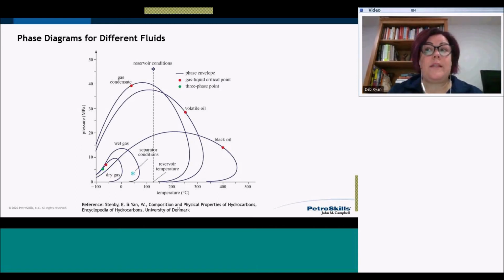So something that we need to be really careful with the characterization of our black oil reservoirs is that if we find a reservoir that has a gas cap over an oil, it means that initially our reservoir pressure is at bubble point pressure. Because in order to have that equilibrium of gas and oil in the reservoir at the same time, we cannot be above that bubble point, because otherwise all of that gas would still be sitting in the oil. So it's something when we're QCing lab reports, and we're not going to talk about how we actually QC lab reports today, it's something that's really important in terms of our understanding of the original reservoir pressure relative to the bubble point pressure in our reservoirs, particularly, like I said, when we find them with gas caps already present at initial conditions.